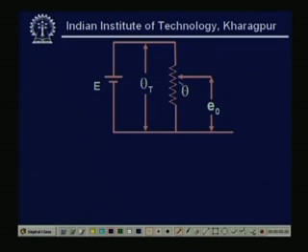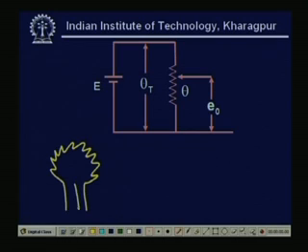So, I have given a supply excitation voltage, and there is a total angular rotation of the potentiometer, because if you look at the physical shape, it looks like this. I have a wiper, or jockey in the case of a rheostat. For a potentiometer or preset we call it a wiper, in the case of a rheostat we call it a jockey, but the principle is the same, both are zero order instruments.